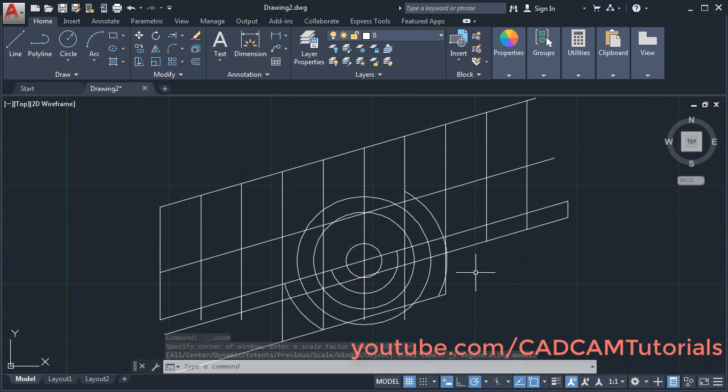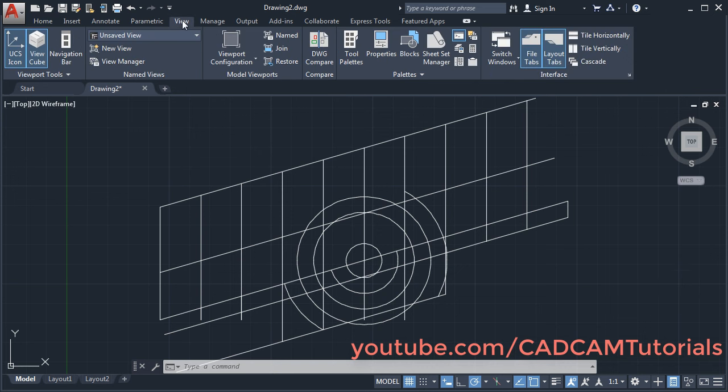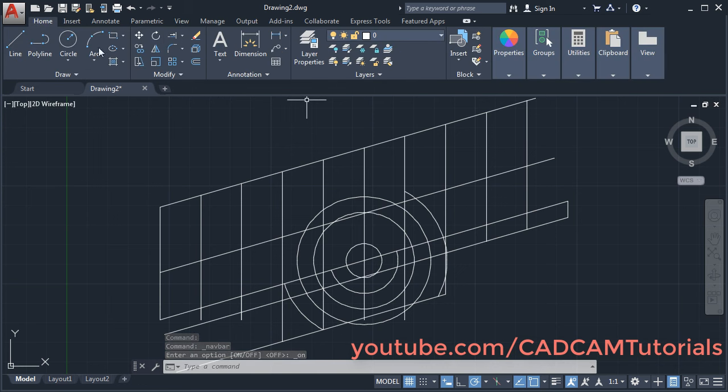Then there are some more commands. Now here the navigation bar is not shown. To make it visible, click on view and click on navigation bar. So it will show the navigation bar. Click on home to come back to the original view.